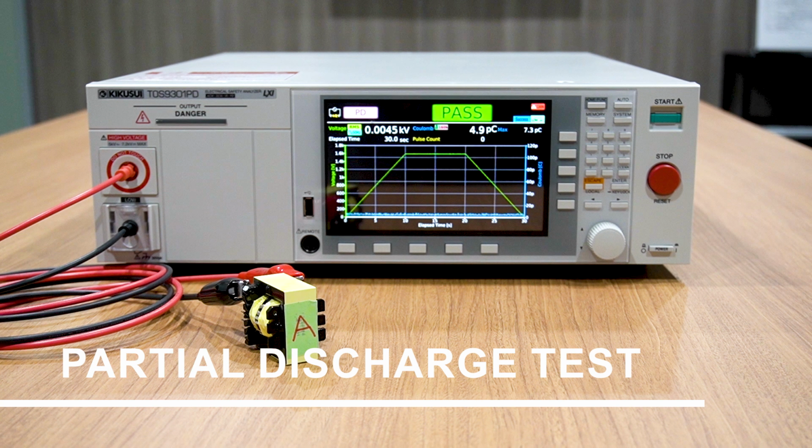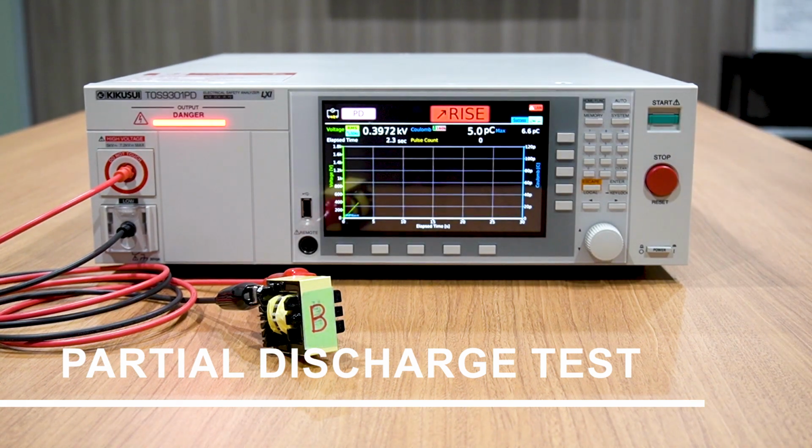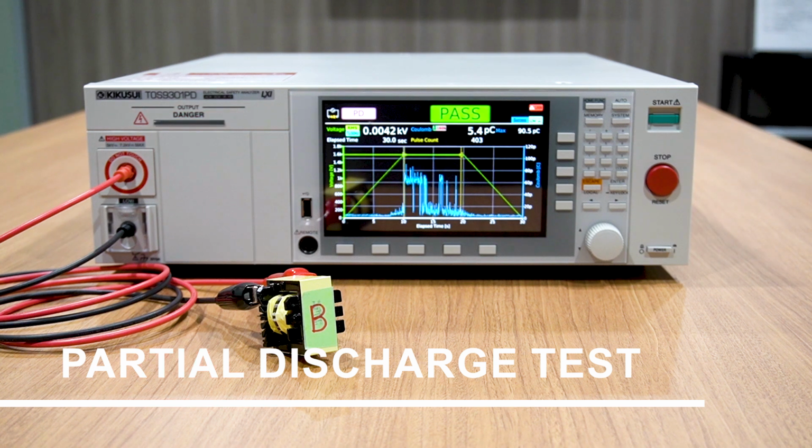Next, let's test sample B. As the test voltage gradually rises, partial discharge begins to occur around 1500 volts. And at 1600 volts, you can see that partial discharge is occurring continuously. In this instance, we did not set the upper charge value, so the test ended with a pass result, but in reality, if you set the upper value, the test will be interrupted with a fail notification.